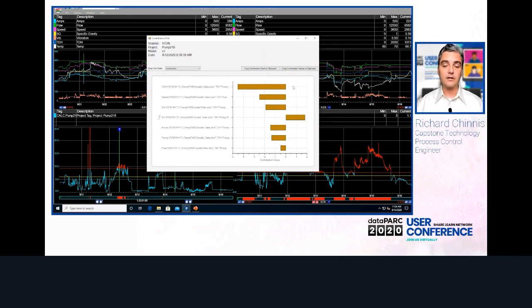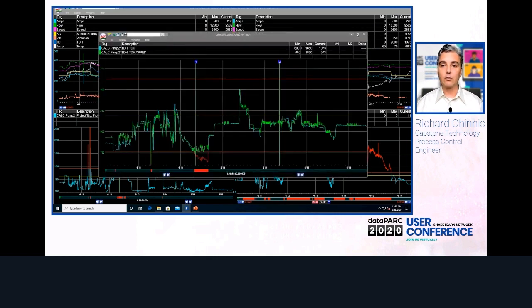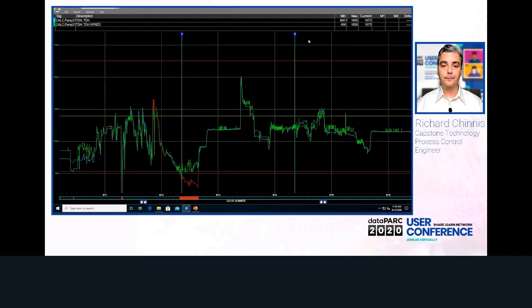So it takes all of the x's and says, okay, for that very specific point in time, at that moment, the HT2N was this number, and here's what was contributing to the HT2N. Well, right here it says total dynamic head. If I left click on that bar, I get a trend of the total dynamic head. The blue is the actual total dynamic head. That is what's coming from the historian. That's what the pump was actually producing.